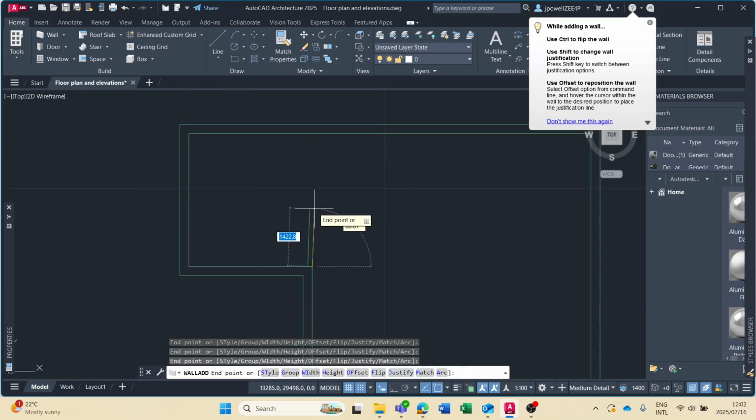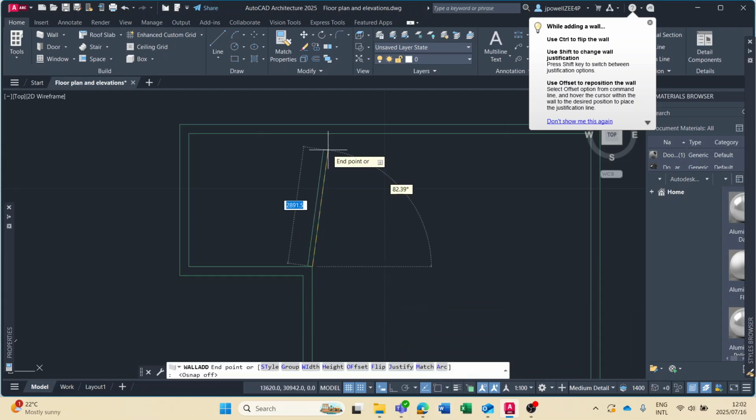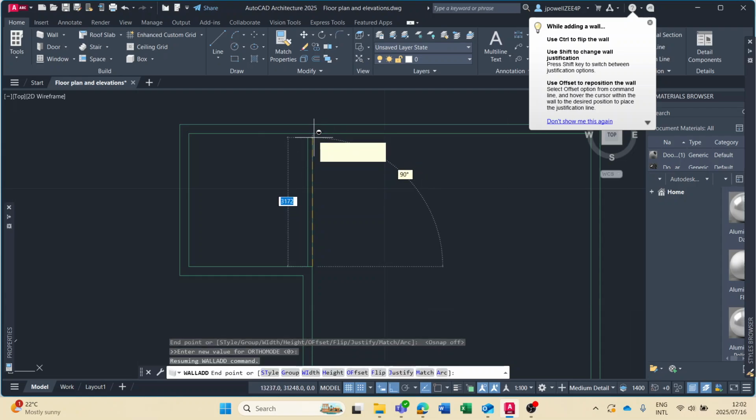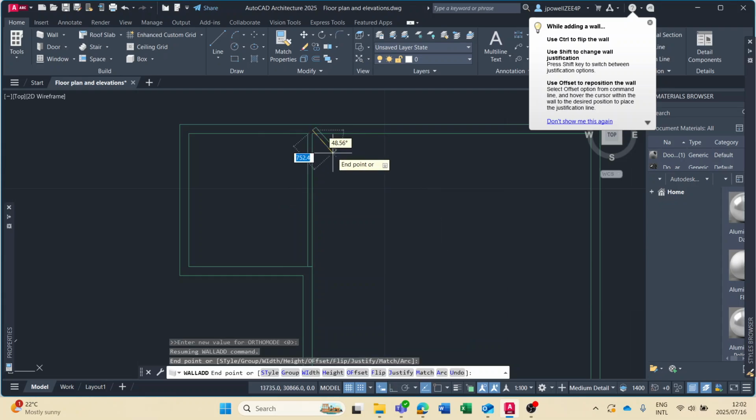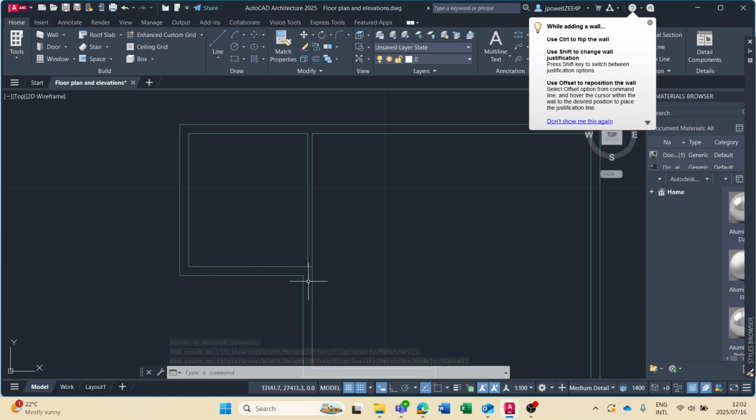Okay, I just want to show you something. Switch off your snap mode for now and hold in your shift button while you are moving it so that it just creates a straight line. Now what you'll see is the wall connects perfectly at the top there, but not at the bottom here. And that's because it's on a turn over here.